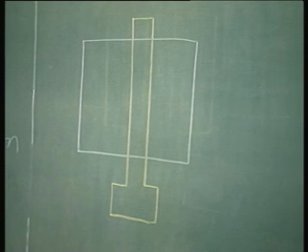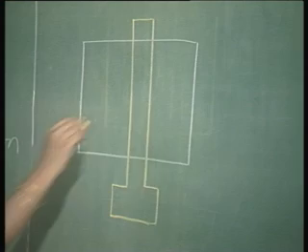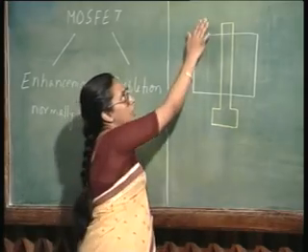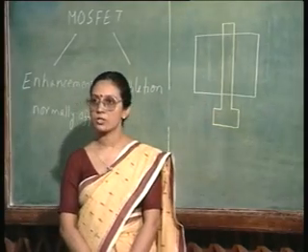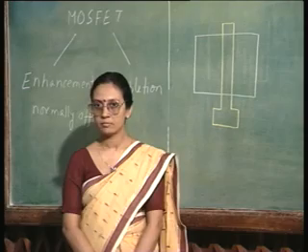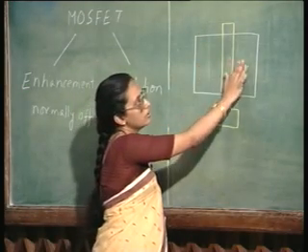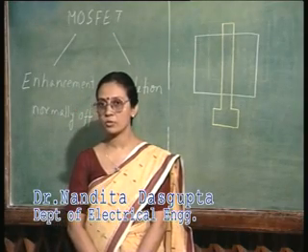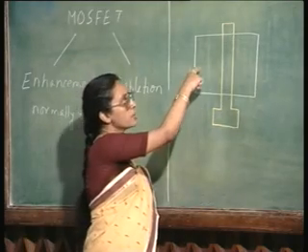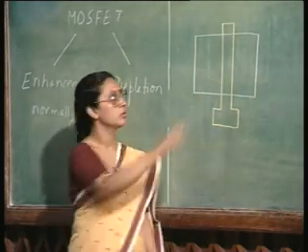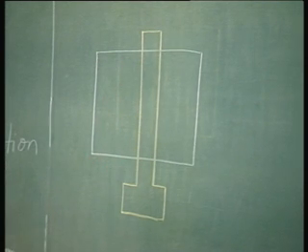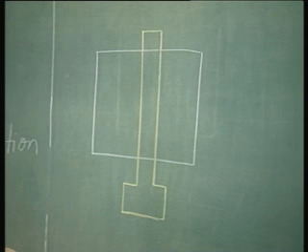Polysilicon itself is going to act as the gate contact. So, underneath this polysilicon line you have the gate oxide. Everywhere else outside this white square it is all field oxide. Okay? So, you have just these two halves of the window. You do not need another mask for your source and drain. You can dope straight through this window. Outside it is all protected by the field oxide and here it is protected by the polysilicon. So, your source and drain are automatically aligned to the gate.